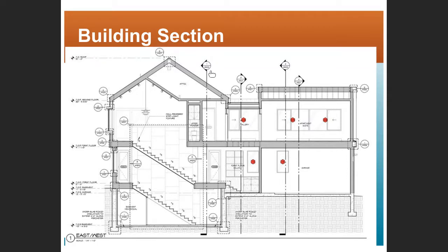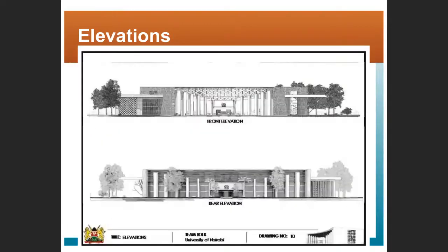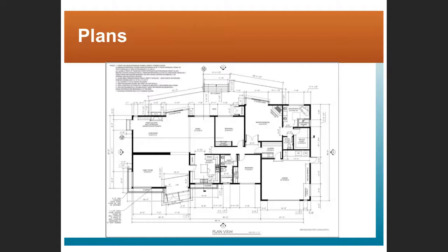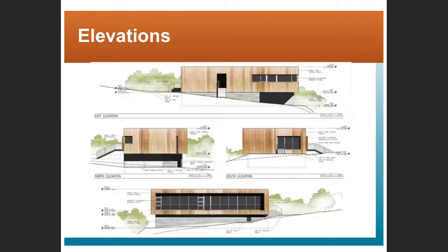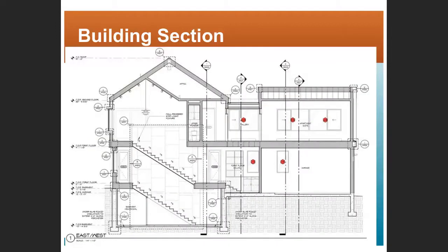So when you're looking at the set of drawings, you have to see how sections and details are related to each other. Let's go back to the plan, right? This particular plan is making reference to other elevations that might appear elsewhere in the drawing set. This section has references to other details that are going to exist elsewhere in the drawing set.